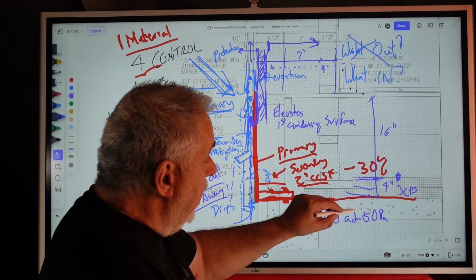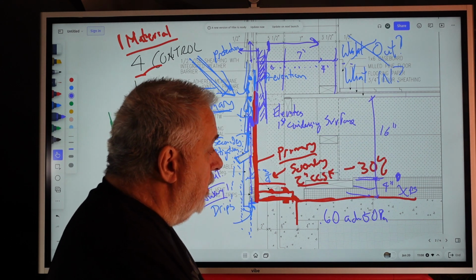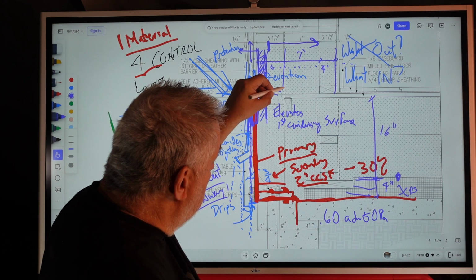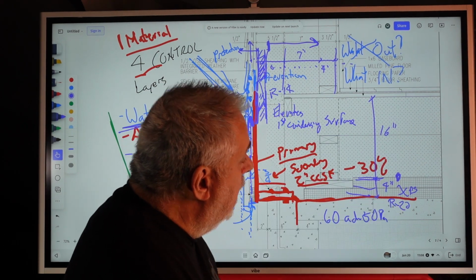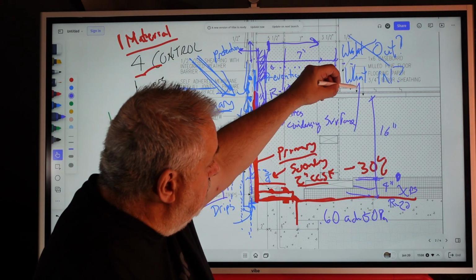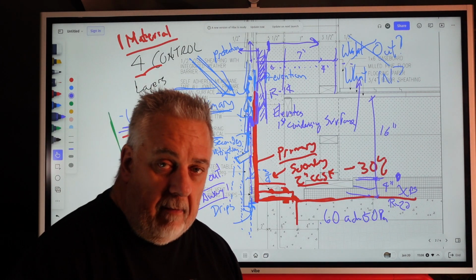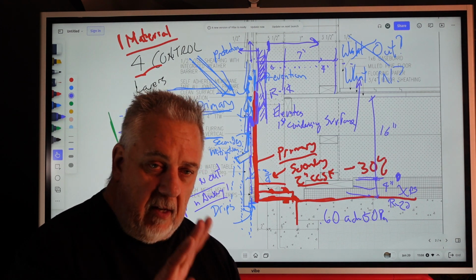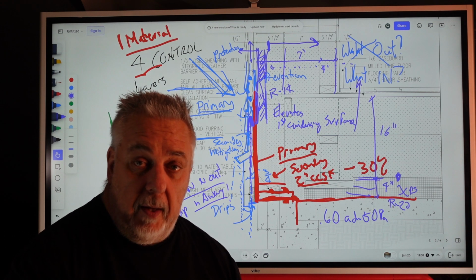And we put it at risk. We basically took this wall, turned the corner, and put it there, right? This is probably somewhere around R14, and we talked about this being R20. So this has the freedom to dry that way, but that really doesn't have as much risk of getting wet as, say, the ceilings or the walls do, unless, of course, a plumbing leak, which we were